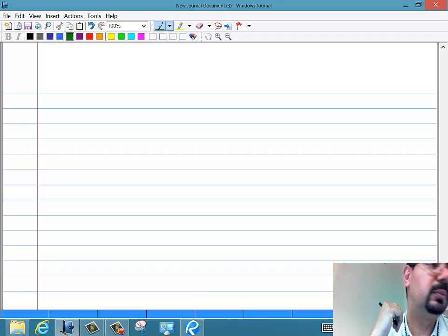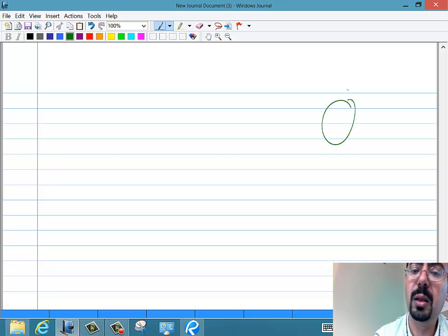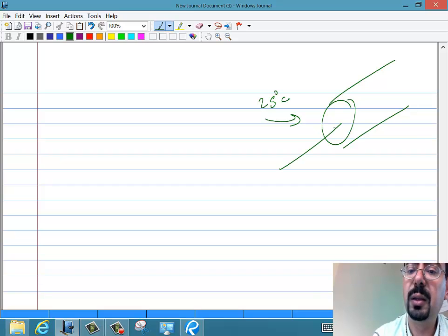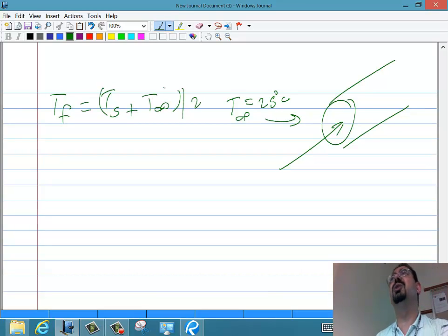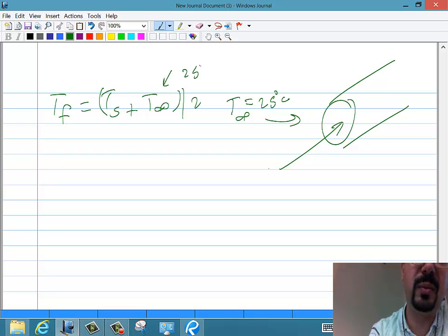So the air is at 25 degrees, correct? So that's T infinity. I need T-film to get my Reynolds number so that I can tell which formula I should use. So, okay, 25 here. What about this guy?